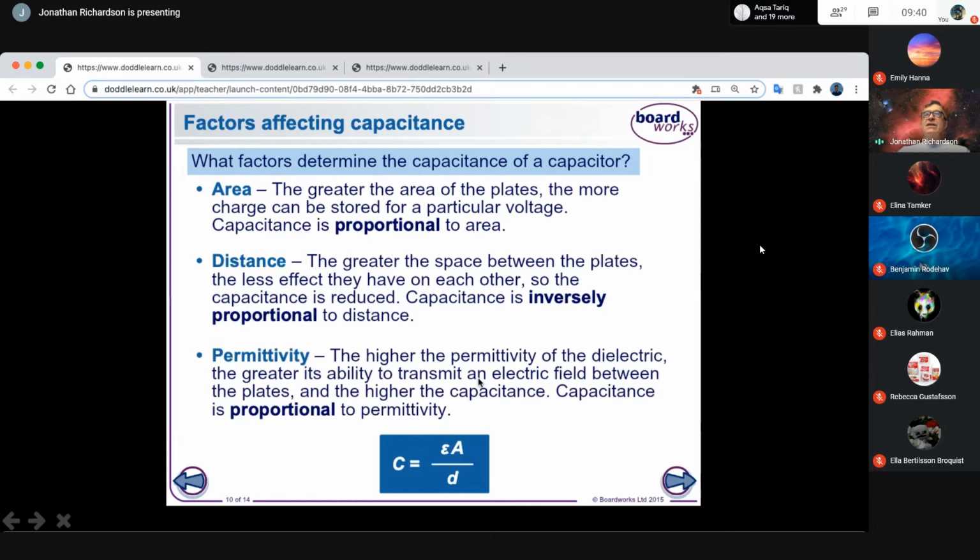Now that tells us that capacitance can be defined through the combination of the permittivity, the surface area, then divided by the distance. So if I took my two binliner plates that you saw yesterday in the video, no worry, Ella, you're here now. If you take the two plates as we saw yesterday, change the medium in between them and made them a bigger distance apart, we would change the capacitance.